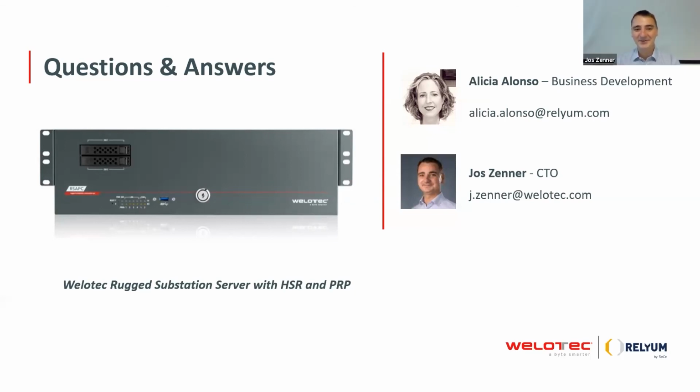Does a Velotech server have built-in systems that support IEC 61850 MMS? No. The server is just a platform that runs applications, so you can run multiple applications on it, and there could be an application from a vendor like Siemens, GE, Hitachi ABB or ABB, or also smaller vendors, or just software vendors like Copper Data and the Xenon SCADA. So you can run those applications, and they usually support MMS.